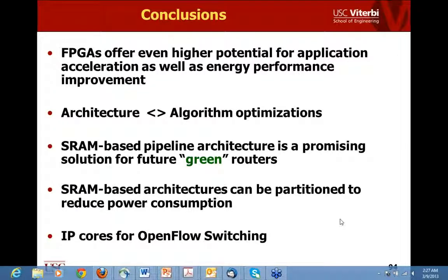Now, for the actual hardware for implementing it, the technology we are using is what is called clock gating, which is available in these FPGA devices. For example, we're using Xilinx devices, where we can dynamically activate or deactivate a particular logic path, and that's what we're doing here. So that gives us control over how to deactivate a particular pipeline. Okay?